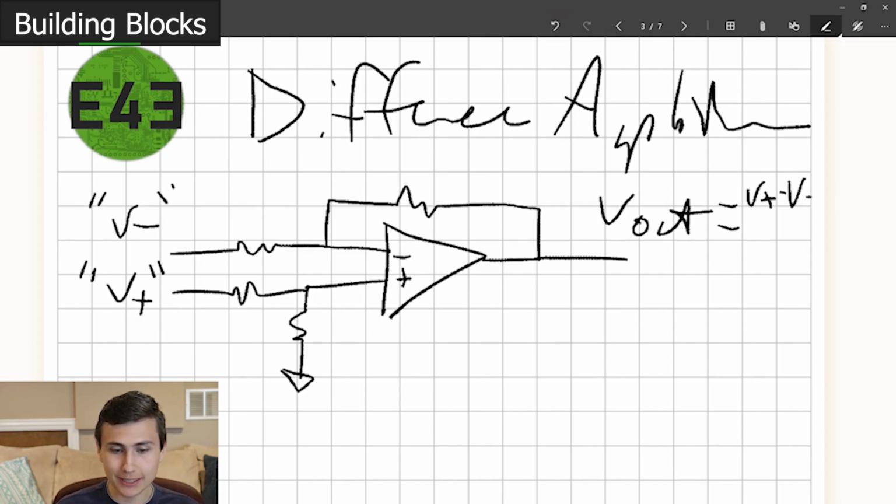So when we're using this in our circuit, we make this Vref, and whenever our output is above the desired set point, we get a negative output here, or a positive output when it's the other way around. So basically, because we're regulating current, we're saying there's a positive error: the output current is too low, I'm asking for more current, give me more. Or we're saying the output is too high, give me less.